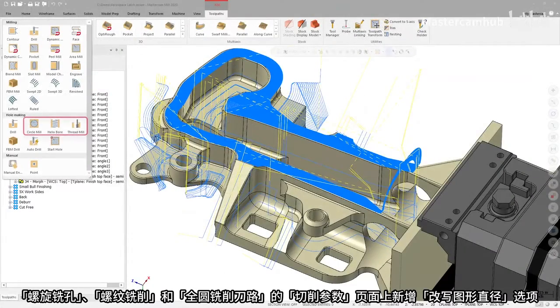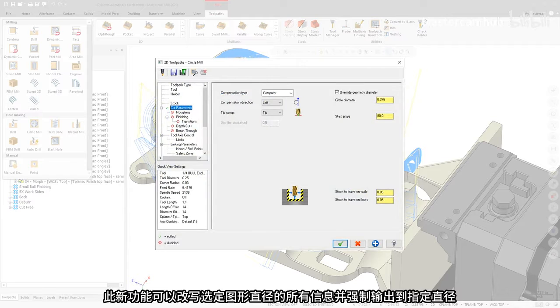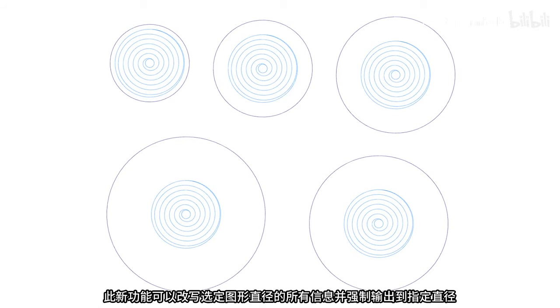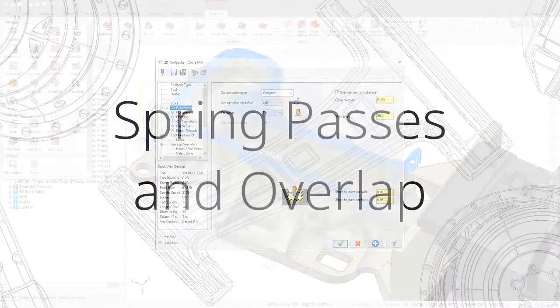Helix bore, thread mill, and circle mill toolpaths now include a new option on the Cut Parameters page called Override Geometry Diameter. This new feature allows you to override all of the selected geometry's diameter information and forces the output to the specified diameter. This option is only enabled when arcs, solid arcs, or cylindrical features are selected.